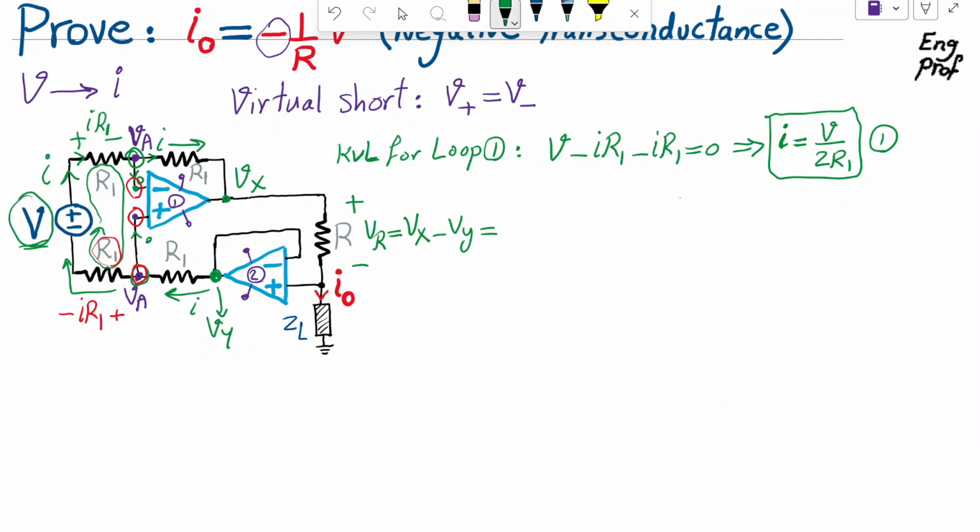It's V because it has the same, let's say, voltage polarity as V, so it's V. But then let's see what's being subtracted from V. Of course, on top we have a voltage drop across the two R1 resistors, and we have another voltage drop across the two R1 resistors at the bottom. So I can say V minus 4R1 times the current I that is flowing through them.